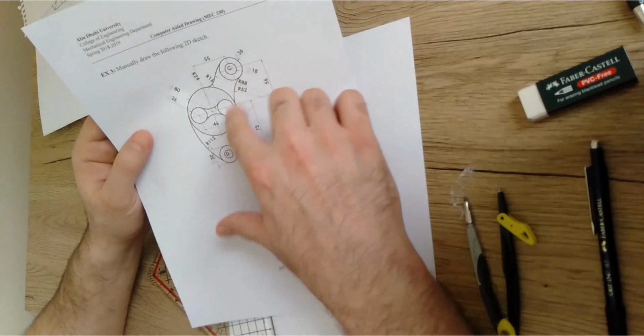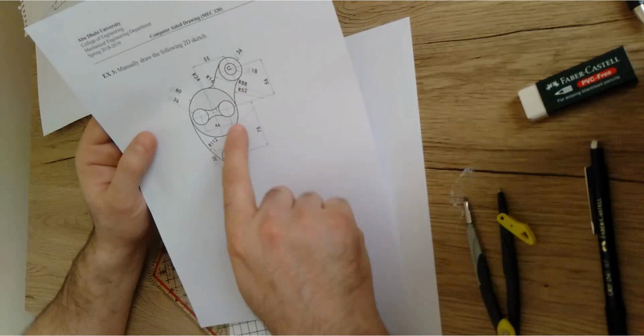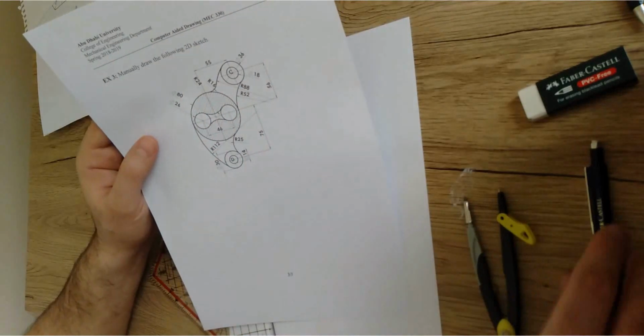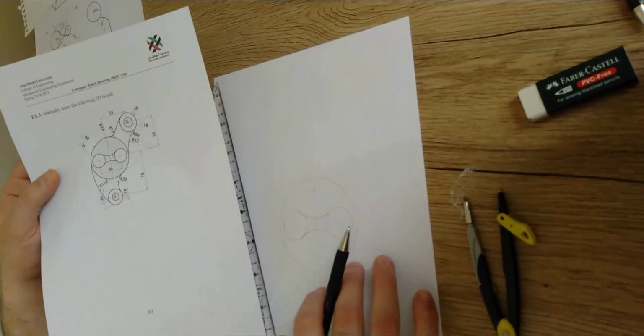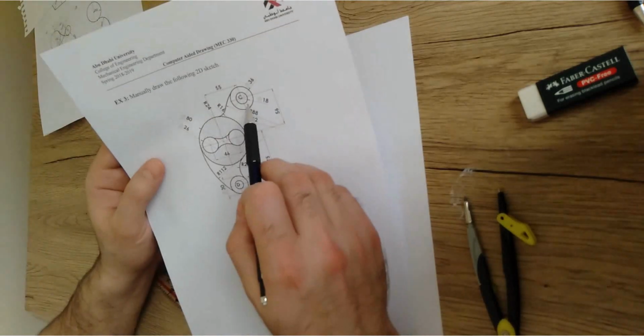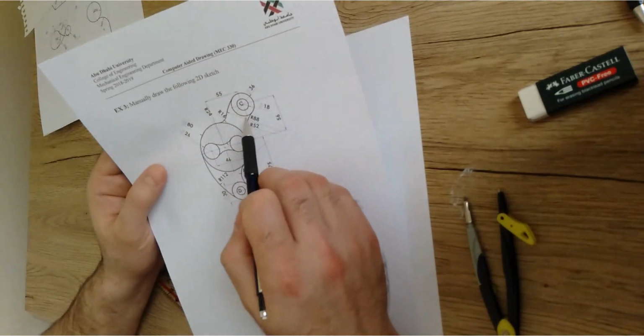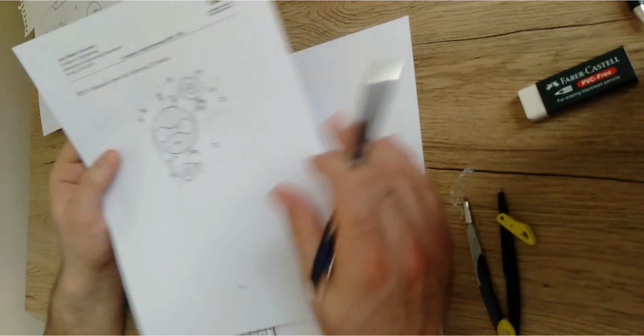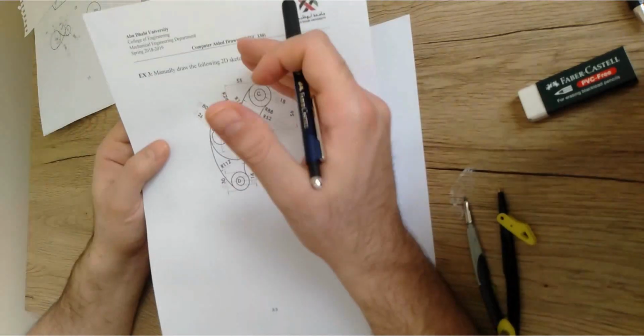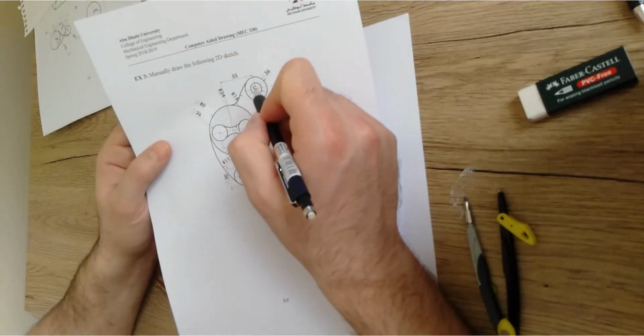We won't be able to draw this curve. Why? Because this curve is tangent to this big curve. The curve, which is 52, is tangent to this big curve, and we already have this big circle. Also, it is tangent to this circle, with the external one with a diameter of 36. But we don't have this circle yet, so we have to draw it first. So that's why I'm going to draw these two circles first.